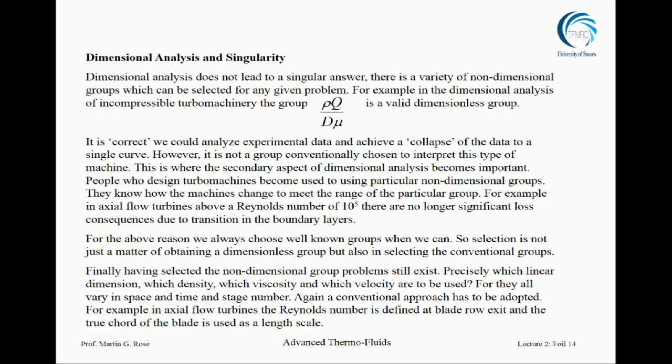The result is, with an LP turbine in an aero engine again, that the efficiency is much higher at takeoff because the Reynolds number is high, the boundary layers are thinner, the losses are lower, and the efficiency is higher. As the aircraft climbs and the pressure falls, the density drops off, the Reynolds number falls, you get thicker boundary layers with more loss and lower efficiency. It's very unfortunate. It drops by about 2 to 3%. And of course it's at cruise that you burn most of the fuel if you're travelling to America or around the world the other way. You end up burning much more fuel because the Reynolds number fell.